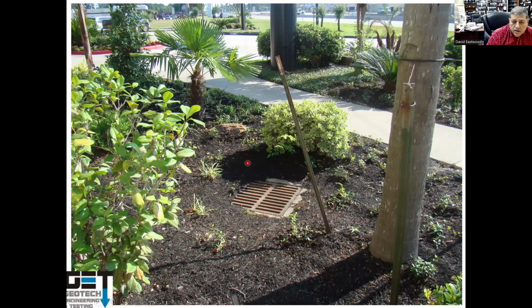Okay, question. Do you have an opinion about sloping a subgrade to a subgrade drain below compacted select fill? Is it really effective? We want to have a 5% slope away from a building in a grassy area and 2% if you have concrete. I don't know what specifically you were saying, but you can slope the ground to an area drain. It could be in select fill. There's no problem with it.